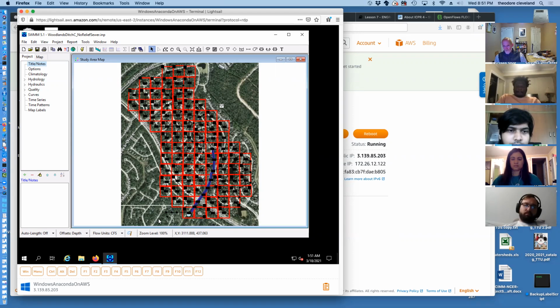1.6 acre cells gives us the ability to estimate average flow depth in a cell and declare whether or not that cell is flooded relative to the structures, in this case, residences that are located within the cell.